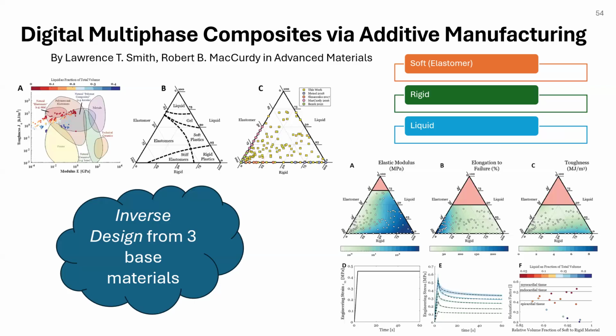So the output, in this paper, what would you fabricate to run the test? A combination of dog bone and compression test samples, depending on how stiff they were. And I guess in those cases, for each one of those dots in C, you would apply the same sort of mixing ratio entirely across the dog bone. True, but every sample was random. So of the N samples that were repeats, they all had clean patterns.